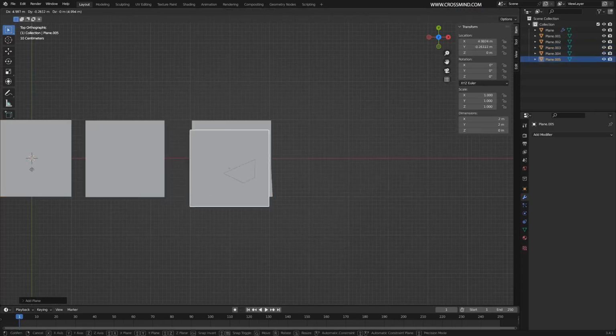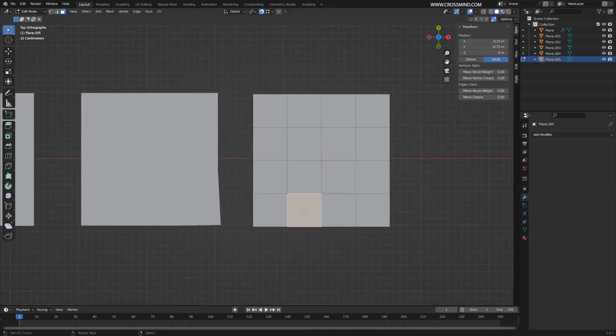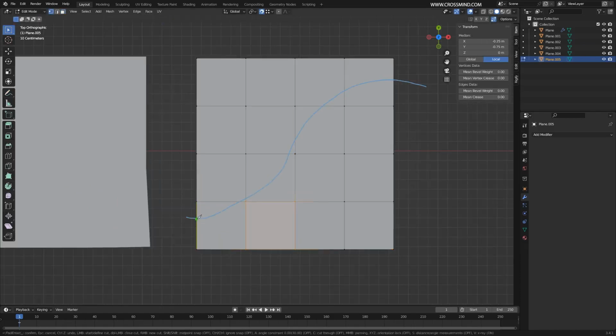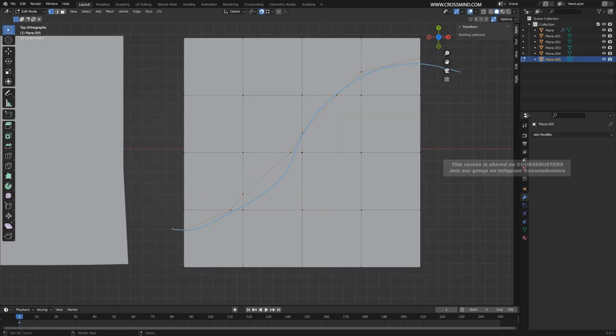Now let's say if you had a grid like this, and in this if you want to make some cut, let's say starting from here, something like this, then you can simply make a cut here. And while you're trying to make cuts, just make sure you utilize quads as much as possible. So this, I'll have to make a triangle, and we are going to convert this into quads later. So one triangle here, and then one triangle right here, another triangle here, n-gon, and triangle, n-gon, and finally one quad. And now I have kind of similar flow, but I need to make few more points here, and I need to convert these triangles and n-gons into quads.